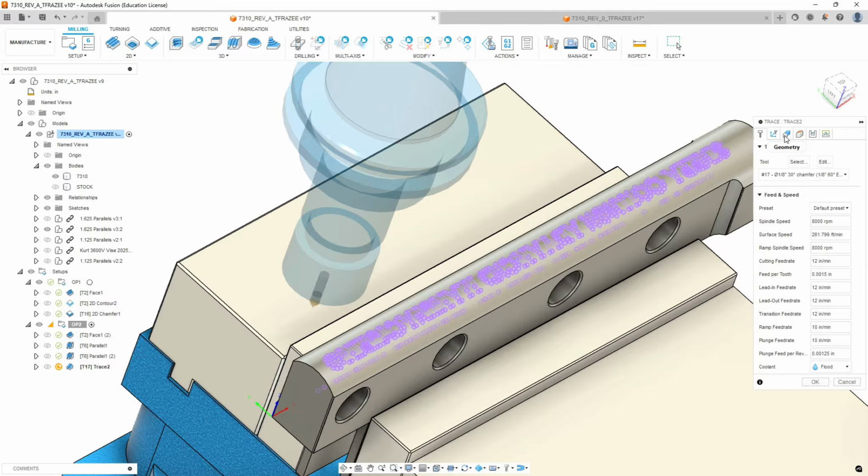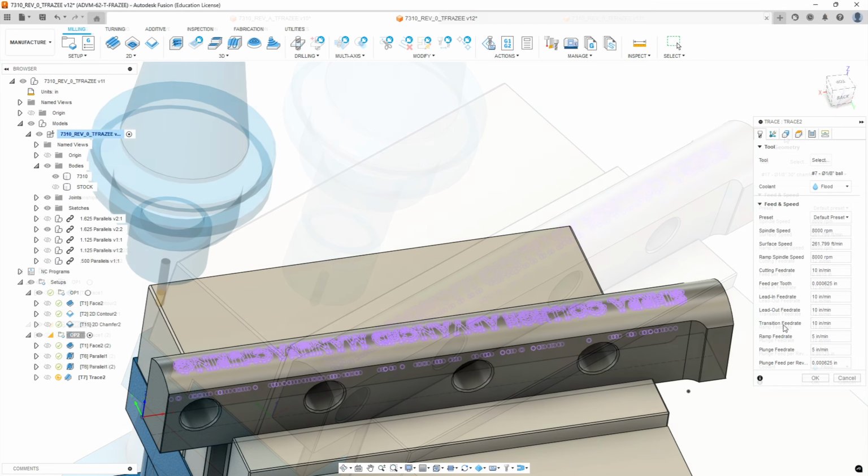So I'm going to actually have you program this so that the text is right on the surface, and chances are there's going to be enough variance between the cutters that you may get it engraved just fine with that, or you may need to adjust this cutter down at the machine. And that's a reason to have this as the last routine as well, so we can restart it. Just leave the feeds and speeds as they are.